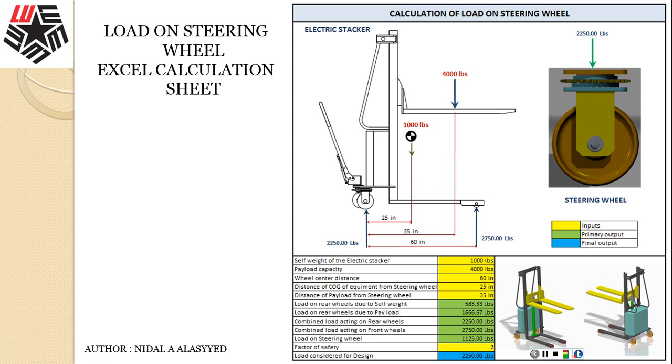I just wanted to feel and sense the new design, because you see on this photo here, I have this new bracket manufactured. I have fewer bolts. I have a cast bearing bush here, with some load applied to it. I want to know what's the difference when the load is applied to this redesign compared to the actual design. I wanted to make sure that the new design is handling the loads properly and avoiding some of the problems that were brought to us by the survey.